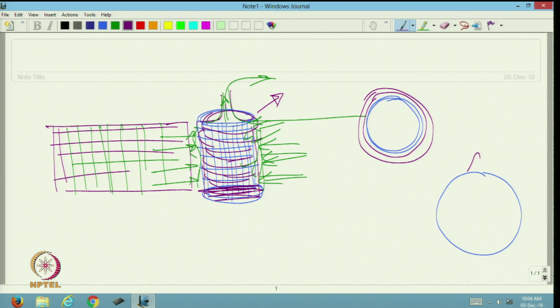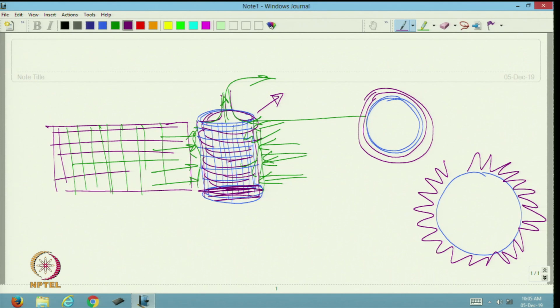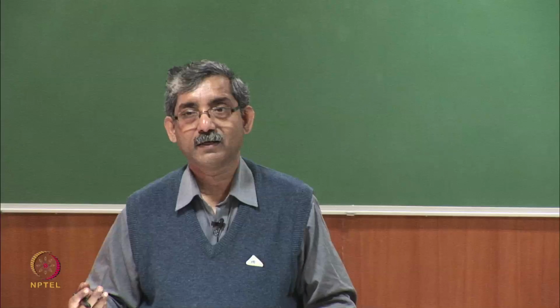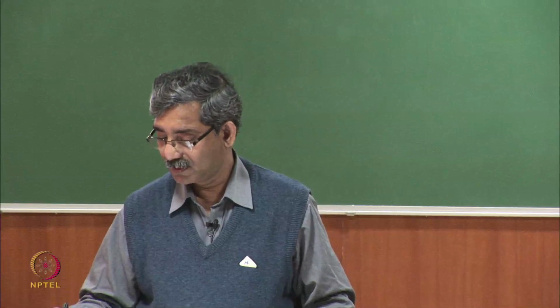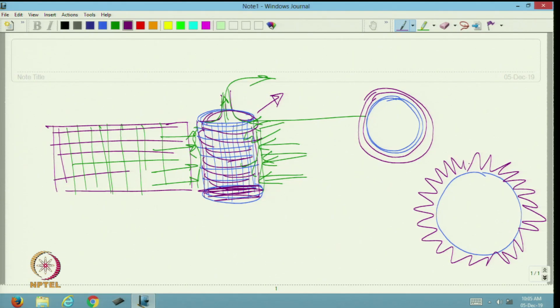So, the filter fabric is wrapped in pleated form, but here the stiffness of the filter fabric should be high. So, we can use spun bonded or heat bonded filter fabric here.